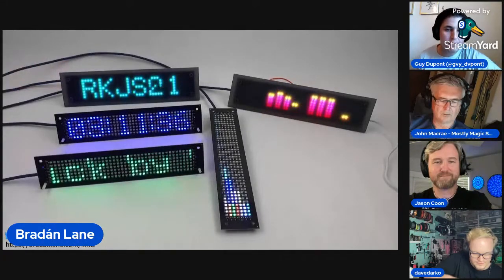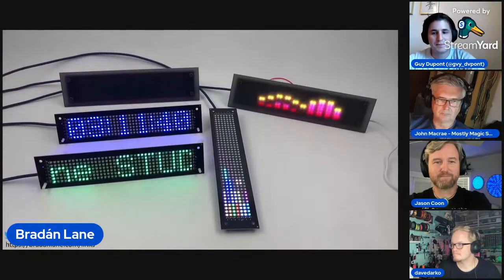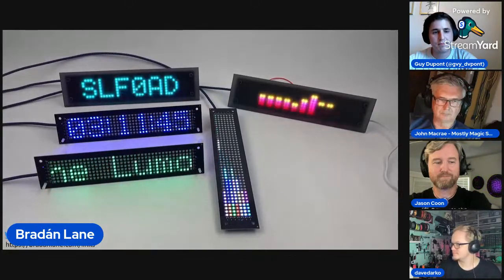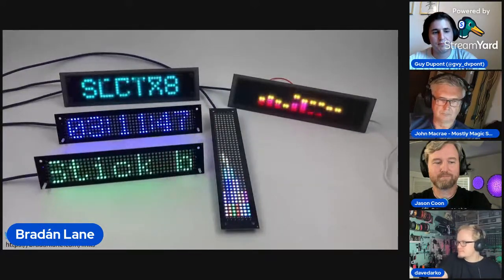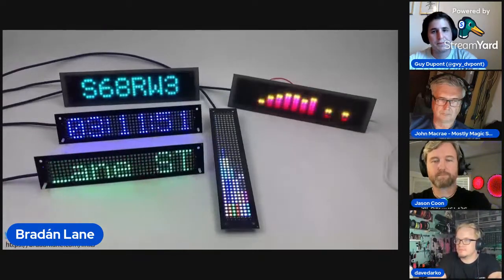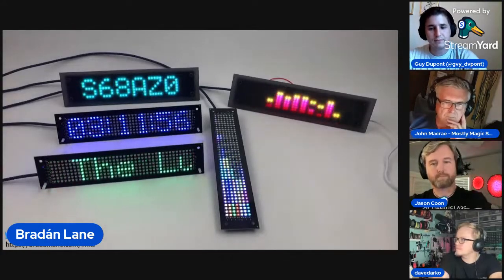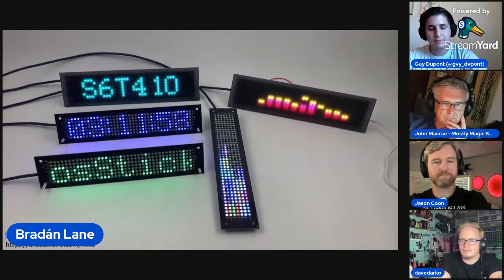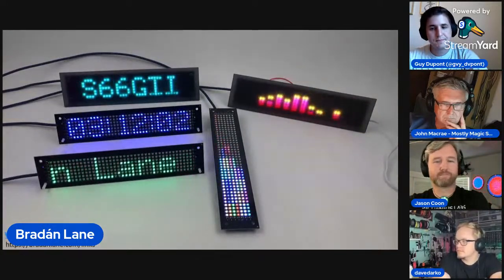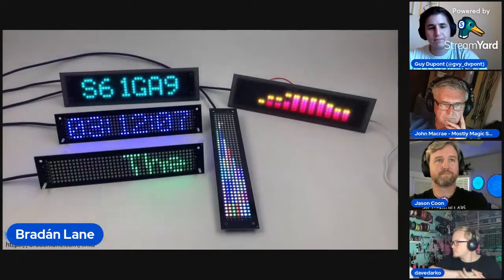I recently created what I call the Lumis Stick. It's 280 LEDs, 7 rows of 4. I make it available primarily with CircuitPython, but of course it can run C code. The 3 demos you see on the side here, the scrolling text, the clock, and my little homage to WarGames, are all running CircuitPython. The little bouncy stick and the spectrum analyzer are running C code using FastLED.